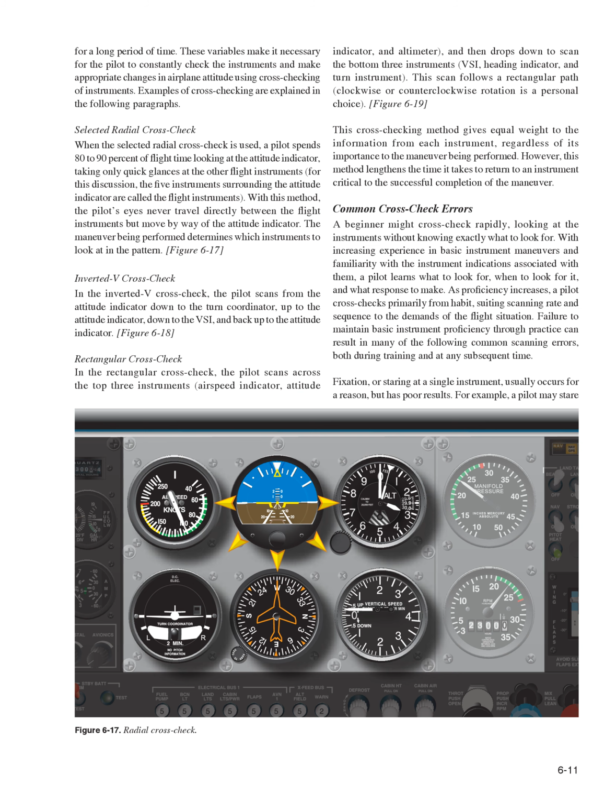This scan follows a rectangular path. Clockwise or counterclockwise rotation is a personal choice. Figure 6.19. This crosschecking method gives equal weight to the information from each instrument, regardless of its importance to the maneuver being performed. However, this method lengthens the time it takes to return to an instrument critical to the successful